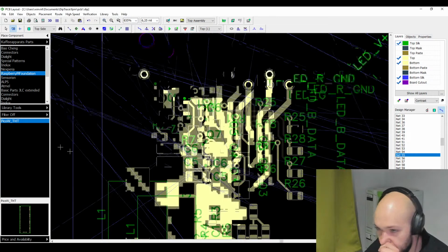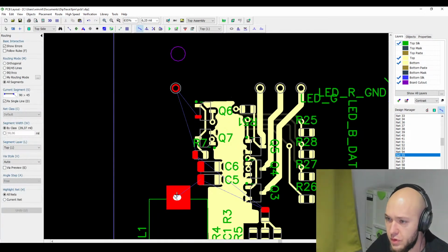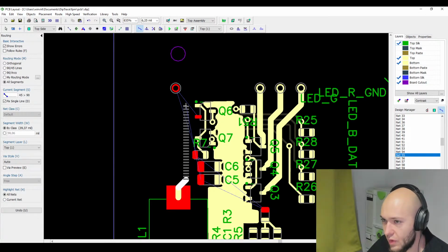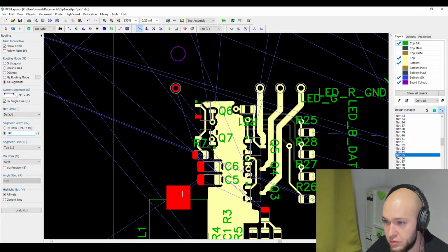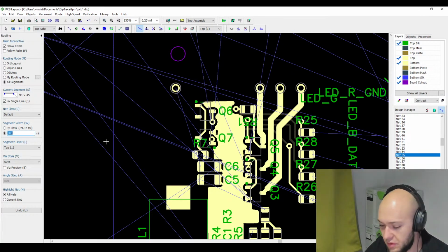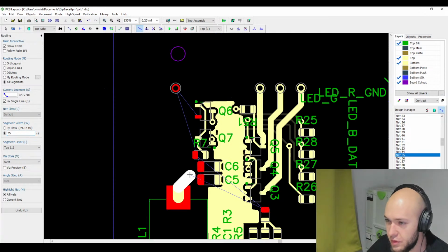So we could use a 2 millimeter trace, and when everything's good, we'll simply use a 2 millimeter trace. 1 millimeter would be sufficient too, but thicker is in this case actually better. So let's go for a 100 mil trace. Oh no, that doesn't look good. Let's do 75. That's also in the range of will work.